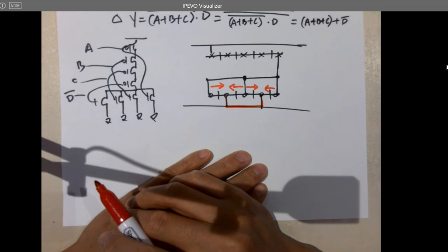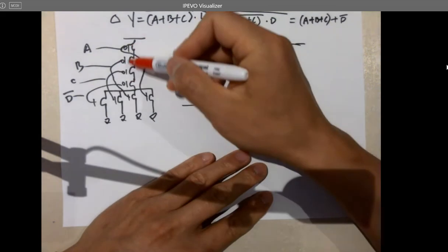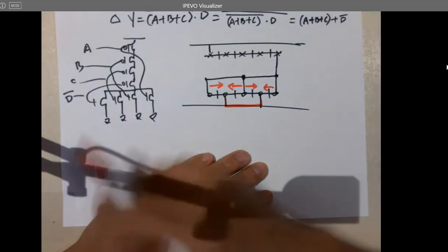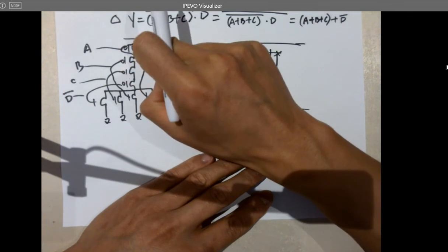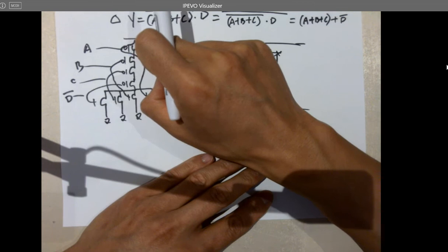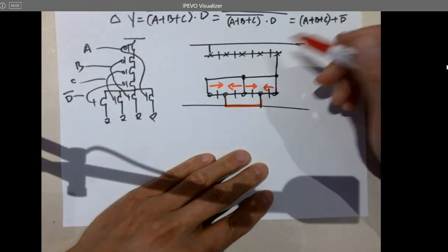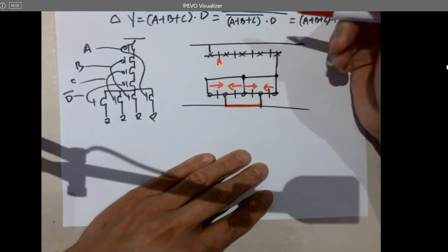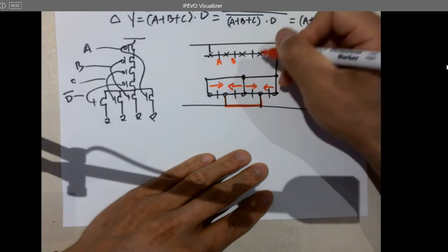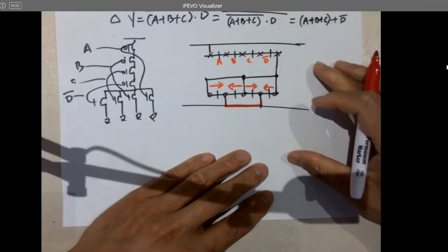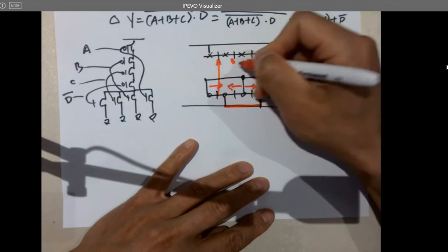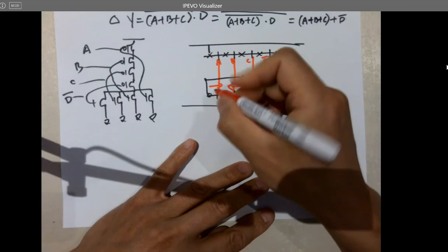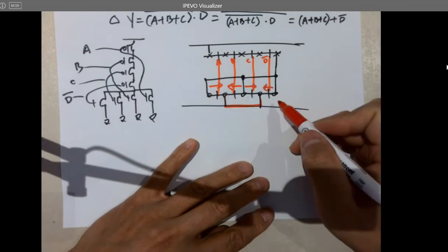So before you do that, look at signal lines. Doesn't matter which is which. The PMOS is definitely has the order, right? Because they are in series. So on the top, this A has to be the top one, just next to the power line. So this will be A, B, C, D naught. These ones are in parallel, so it doesn't matter. I can directly just short this one to here, here, here, here, and these will be ABCDs.